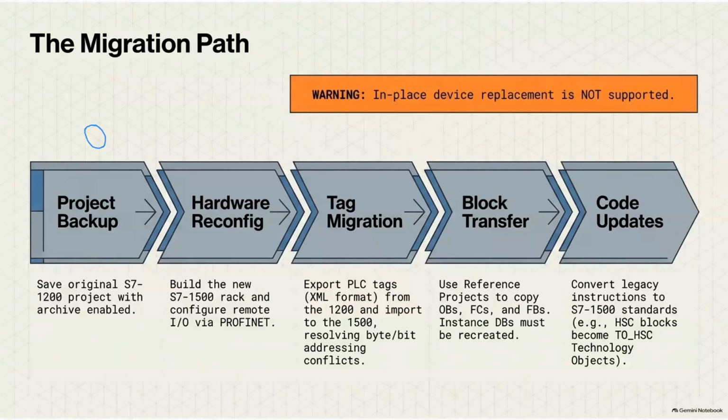So in the back end, a tag name will be given for that button, and that button will be linked to the PLC IO device, IO tag. So this tagging will happen manually for S7-1200, whereas for S7-1500, sort of advanced systems, this tagging happens automatically.